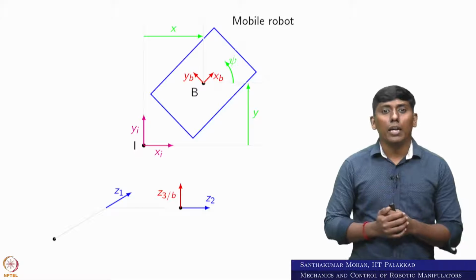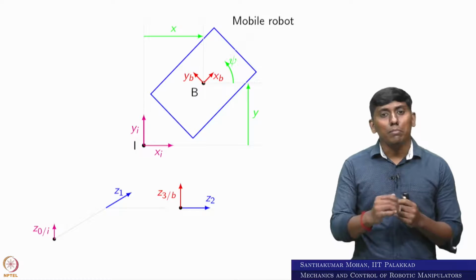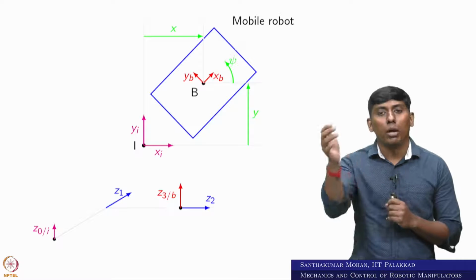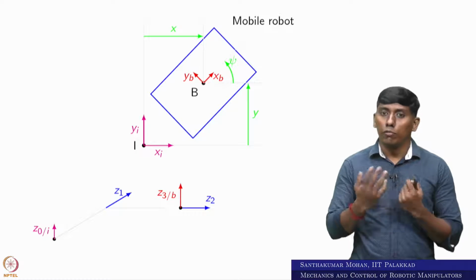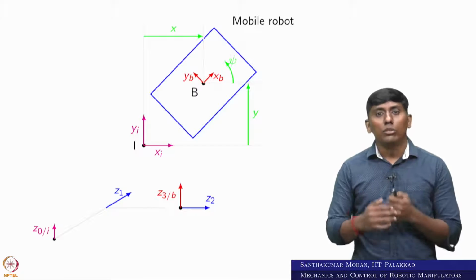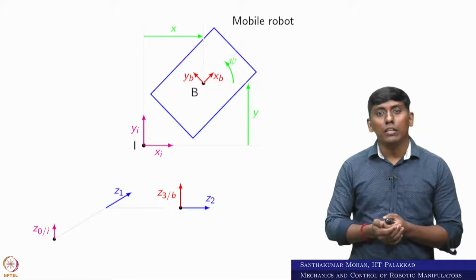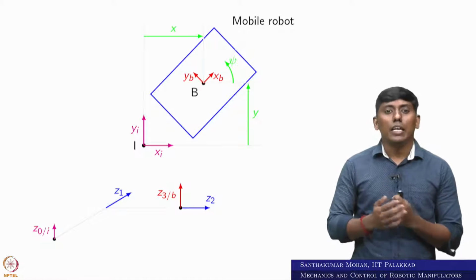Now what I am trying to see is, from the initial frame, which I assume is this one, how it goes from one frame to another. So now I want to derive this using the Denavit-Hartenberg approach. For that, you need to know where the x axis is coming. So the first x axis, which is x0, can be written in that way.